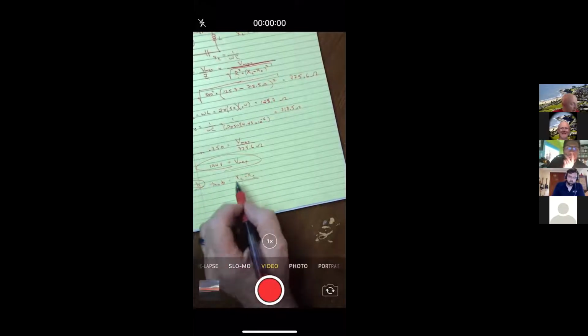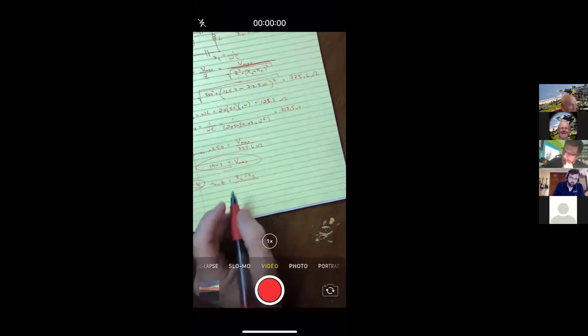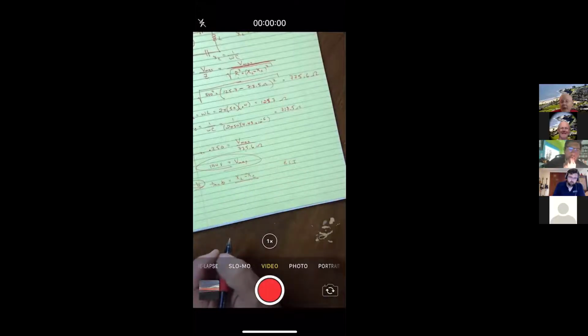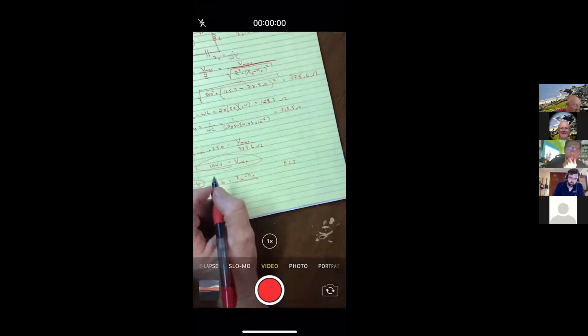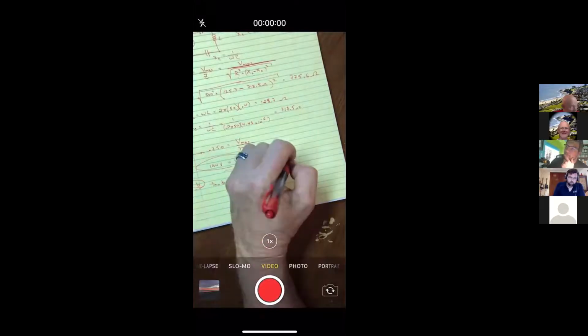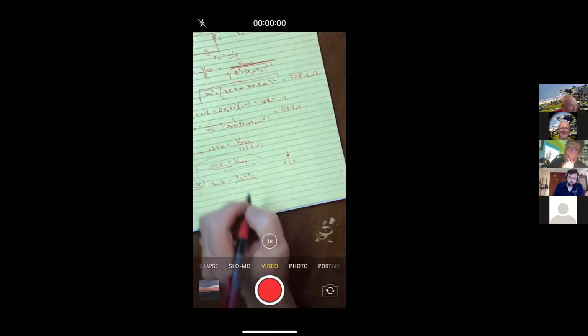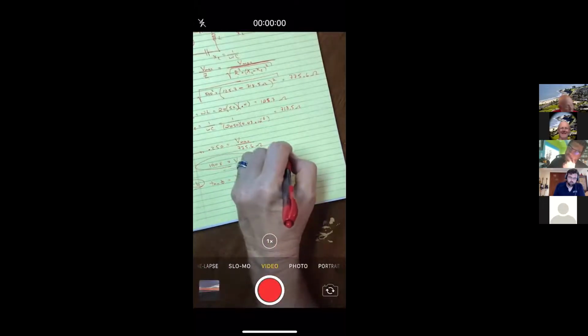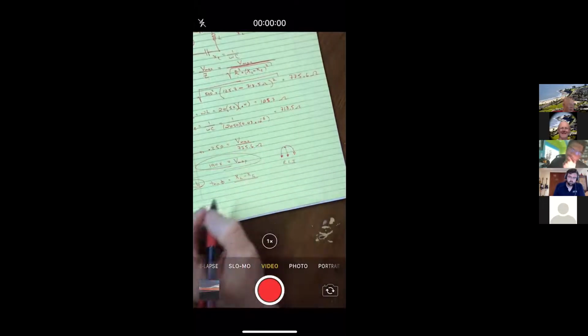So the positive numbers is what we get from an inductor. And so for an inductor, I like to use the word ELI, as I was explaining in the lecture, because of Faraday's law, voltage would lead the current, and ELI is a good way to describe that, because you've got the L for the inductor, and then you've got the E for EMF, which is before the I for the current.